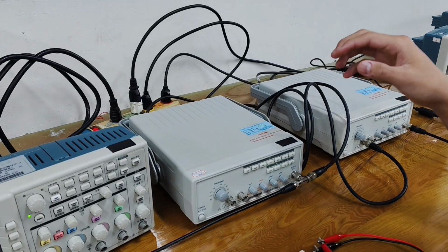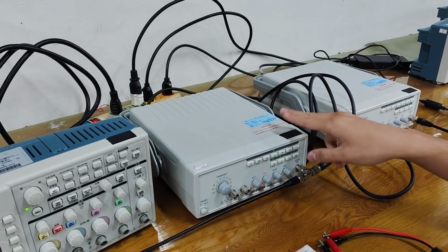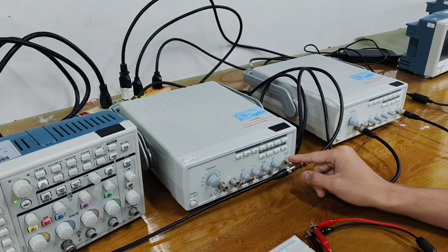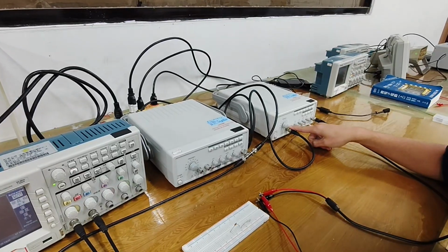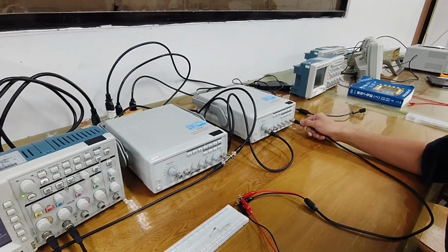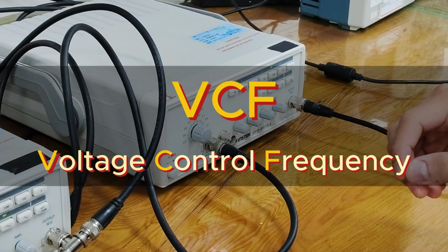To generate a voltage-controlled frequency signal, we use two function generators. The output of the first function generator provides a control voltage, which is connected to the frequency input of the second function generator. As a result, the frequency output of the second generator varies according to the input voltage. This is known as voltage-controlled frequency.